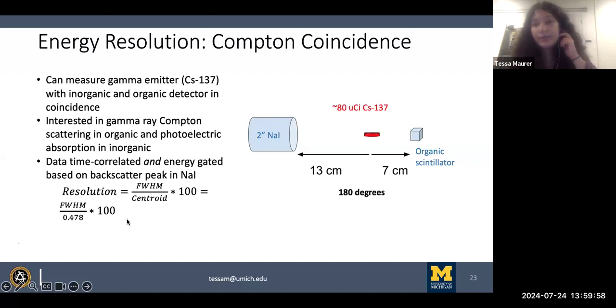Oh, and about the durability, whoops, I missed that part of the question. The durability is the main thing we have to worry about is that recrystallization that'll happen. So it's going to want to get to a more thermodynamically stable state, crystal. And it's going to want to try to pack into that crystal state as much as it can. But then what happens is it's not going to be clear. It's going to scatter light preferentially. It's not going to be ideal for our scintillator purposes.